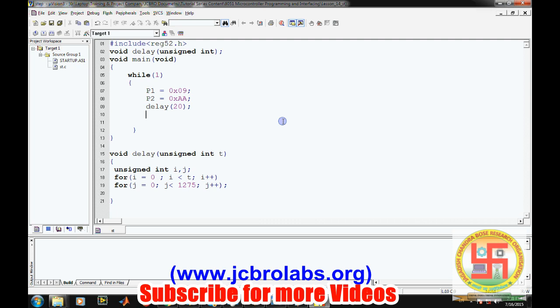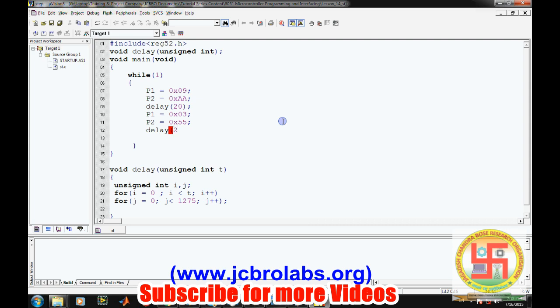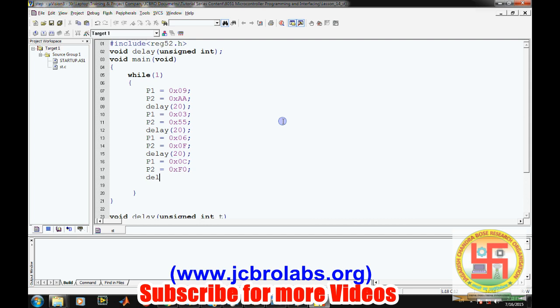If this delay is high, you can visualize the stepper motor taking small steps. Then P1 is equal to 0x03, and then again P2, let's send some other command, and then delay. Then P1 is equal to 0x06, and then P2 equals 0x0f, and then delay 20. Then P1 is equal to 0x0c, and then P2 is equal to 0xf0, and then again delay.